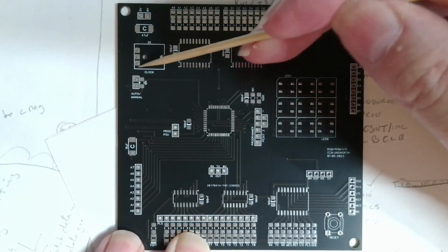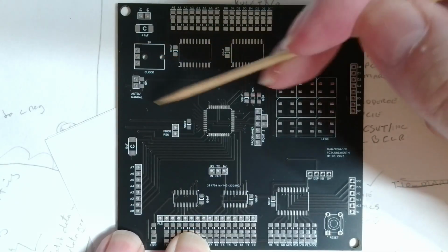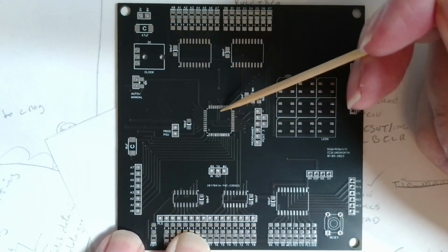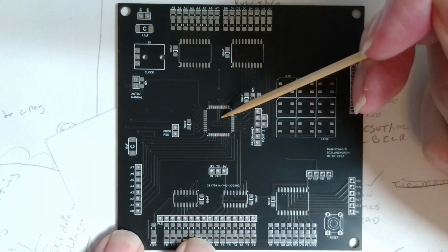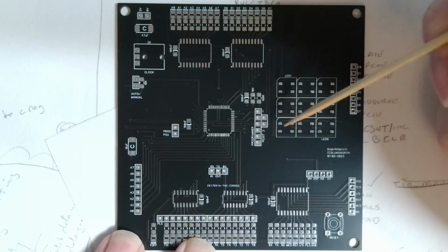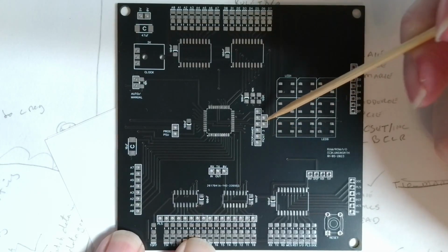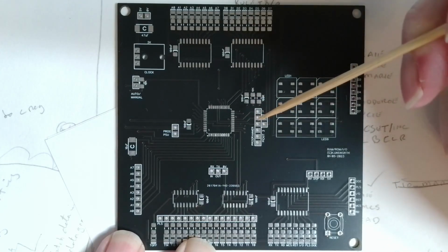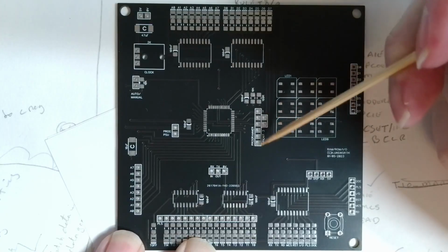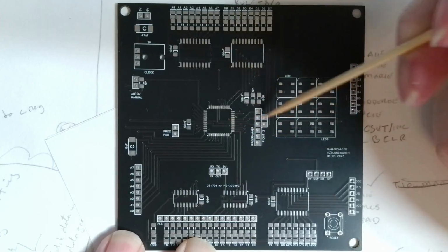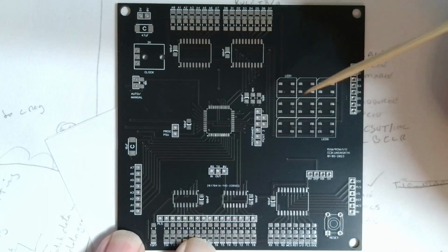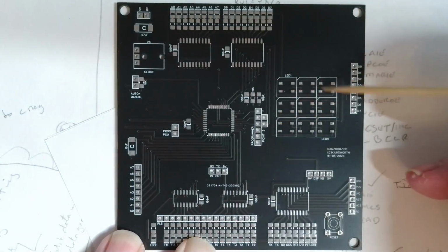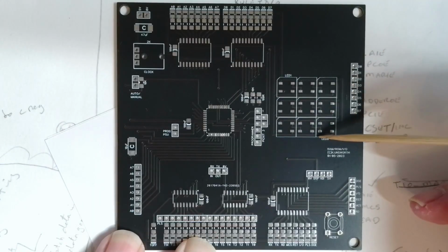Here is where the pot sits for the speed control. This here's a little jumper for the auto manual, again as shown on the block diagram. Here's where the actual PIC processor sits, and that's the programming port. It's these two little jumpers here, where you can jump across so that the pins coming in here are also used for the programmer. But when you're not using the programmer, when the thing's all active, you just want to link across. You've got D0 and D1 on your data bus. Display LEDs, tricolour LEDs, all serially addressable.